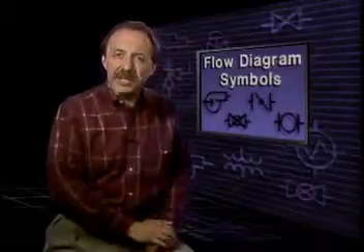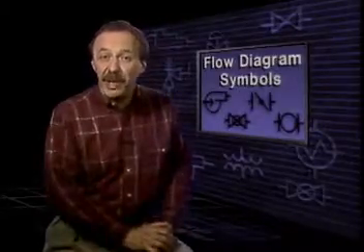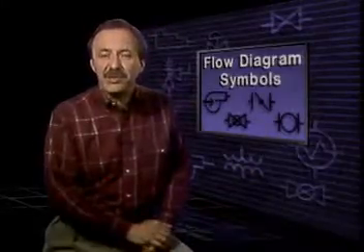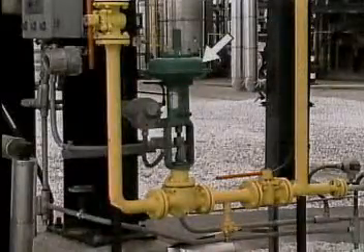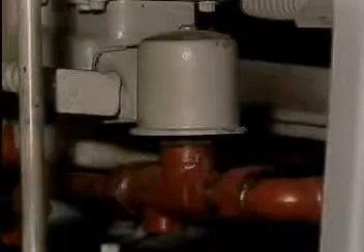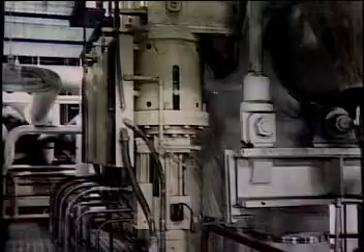Process systems typically contain more valves than any other kind of equipment. Some are operated manually with a hand wheel or a lever. Others are operated by devices called actuators. The most common actuators are pneumatic or air-operated actuators, motor-operated actuators, solenoid-operated actuators, and hydraulic actuators.